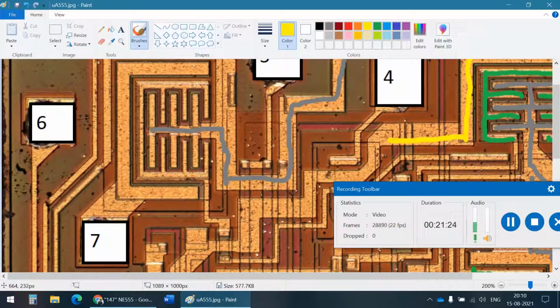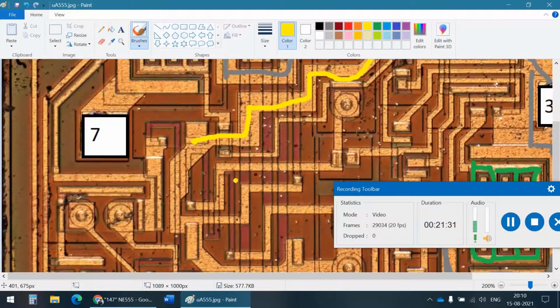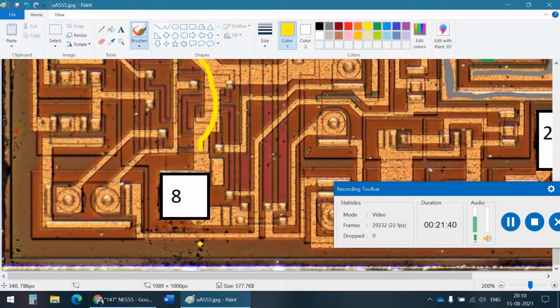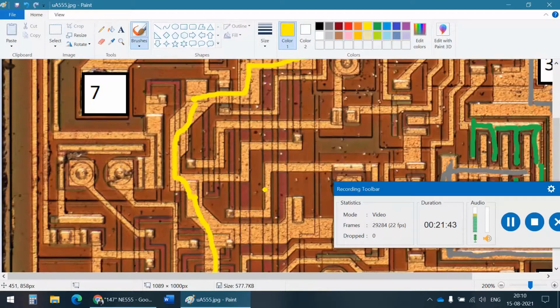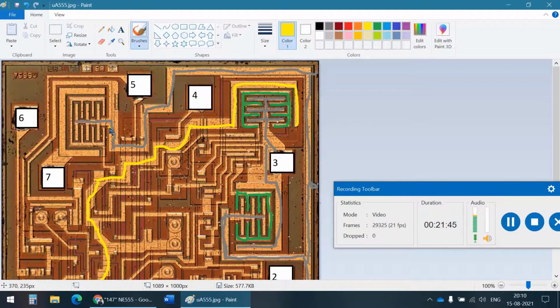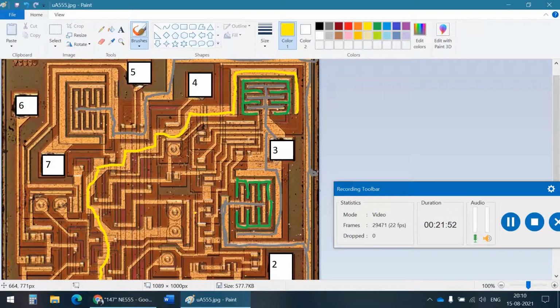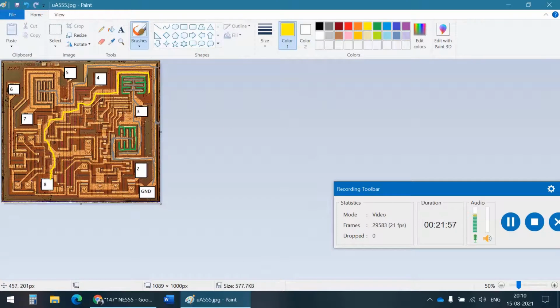Let's go ahead and see that. Yes. Okay, seems about right. Going like that, yeah. Seems about right. And go down through that, and oh, we reached pin number 8, which is VCC. So we're right. The collector pin is connected to VCC. Cool. So yeah, we have identified quite a bit now, the three big things.